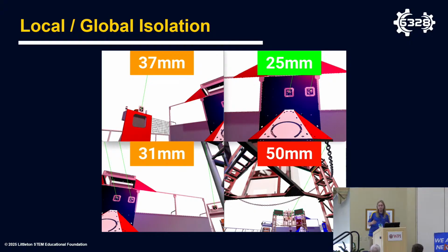Well, first, maybe not. We have used April tags for doing this type of localization since 2023, so for the past 3 years. And it was only this most recent year that we started explicitly separating local pose estimates from global pose estimates in our code. In a lot of cases, you can actually implicitly switch between these estimates using a single pose estimator. Here's an example of what I mean.